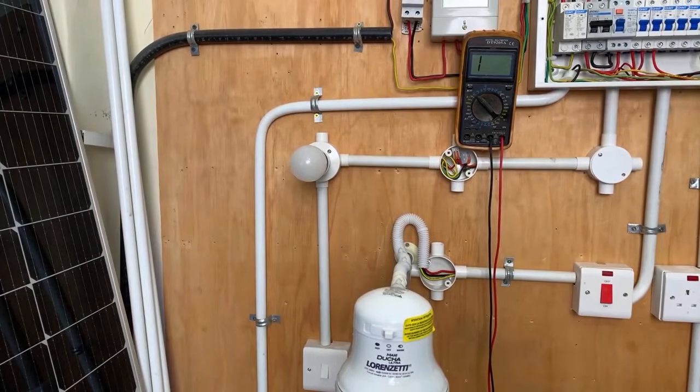Can we intentionally short circuit live and phase? We will not turn it on, for safety reasons. Do you allow me to do that? We'll not turn it on, but for us to record that continuity, it will be of very much help. What do you think, my top bosses? It's all about coming up with problems that didn't exist, but that can exist. So we can short circuit the phase and the neutral at the lighting point, and then we'll demonstrate that indeed that is the reason why an MCB can trip.